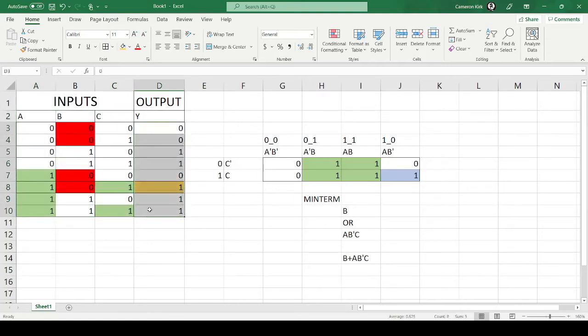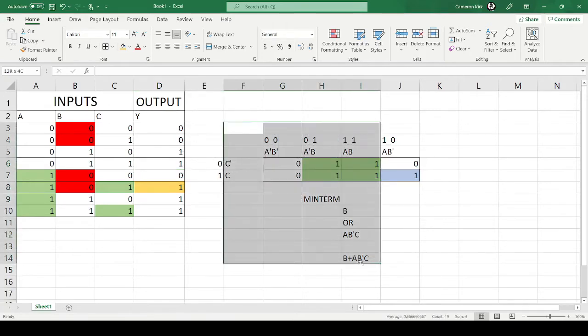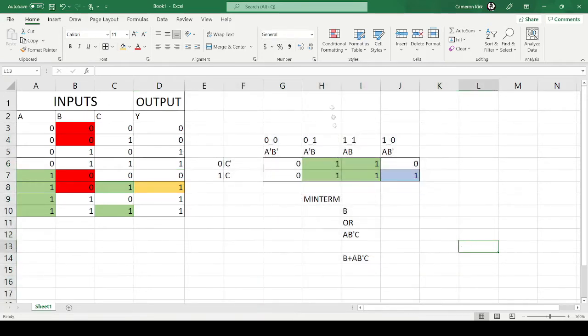So we want every single possible combination of inputs, and then we get to make up for our special situation what kind of behavior we want our LED light to do. So basically we're gonna say, hey, I have special cases in here. These signals mean something to me, and when this one's doing this, that one's doing that, I want it to be true, and I'm too lazy to figure out the logic myself. I want a systematic way of deriving that equation, which is the K-map.